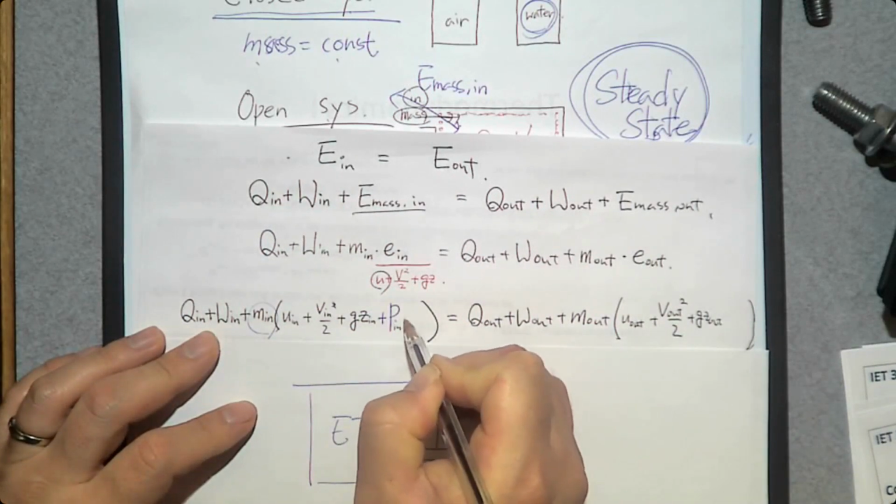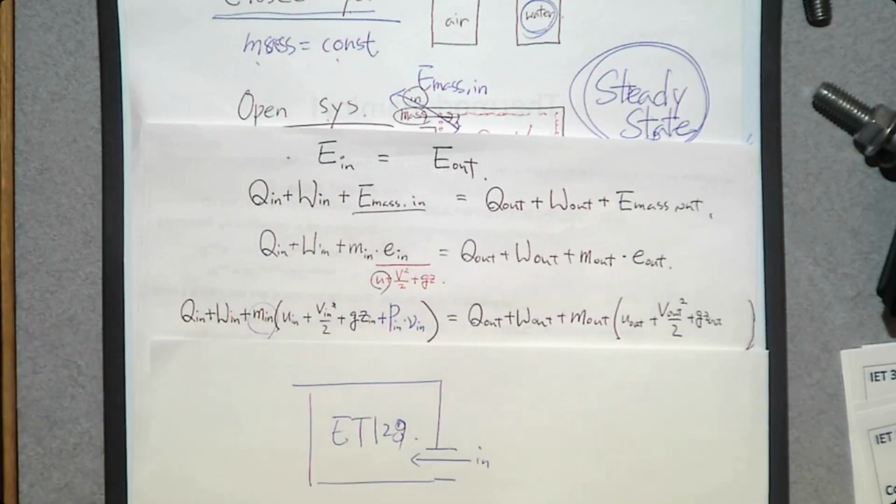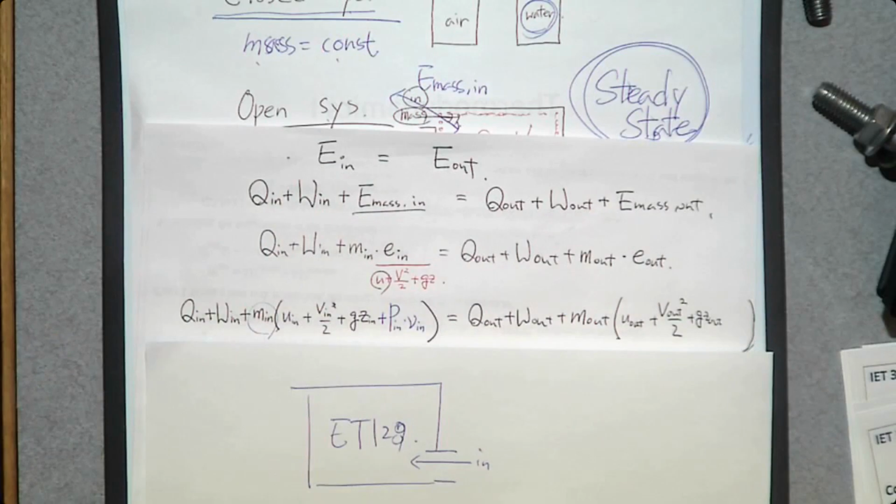Pressure times specific volume. That is the energy work that I need to provide if I want to enter this classroom. That's what you did when you entered this classroom? Yes, you did. But did you feel it? The energy? No. Why is that? Because this room was filled with air, which is compressible. So when you walk, you are actually pushing the air molecules in front of you, but you don't feel it because you are too powerful. You're solid. Pushing the gas is super easy.